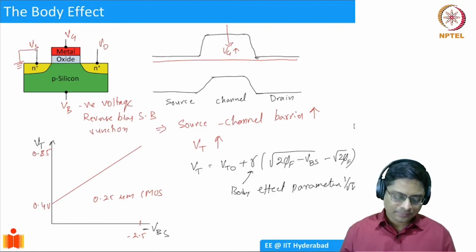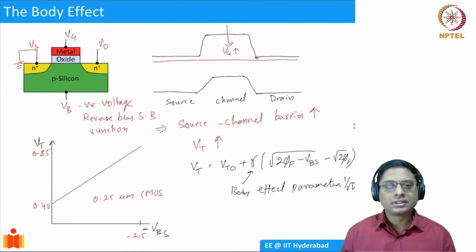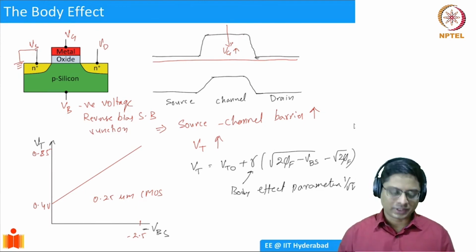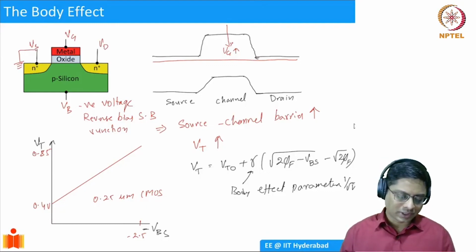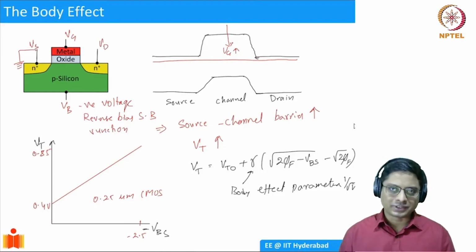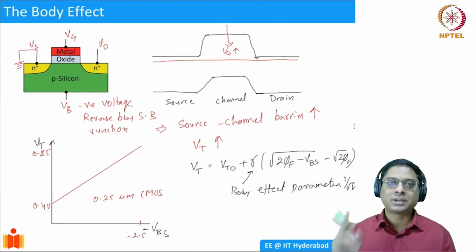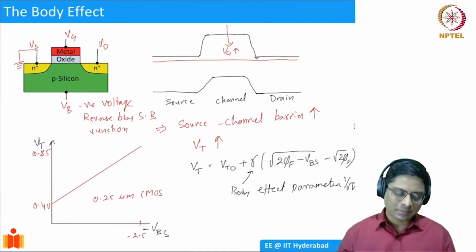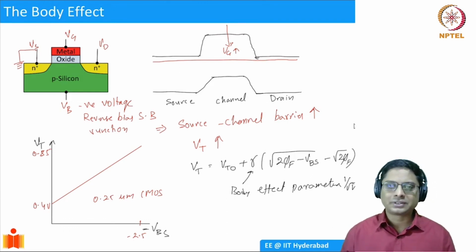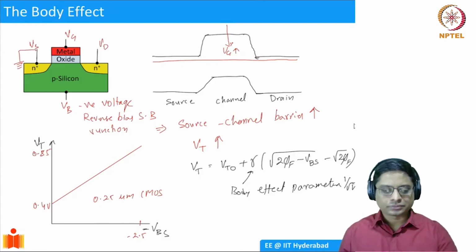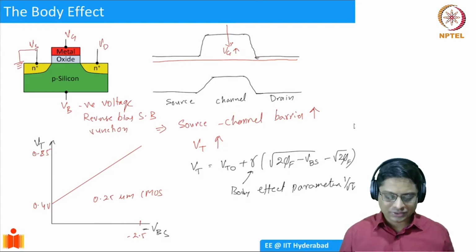So that's why typically in MOSFETs, we ground the bulk for an NMOS device, so that if I apply whatever positive voltage, I'm going to reverse bias it. It will never go into the forward bias. Similarly, for a PMOS device, I'll tie it up to the supply voltage, so that if I apply any other voltage, it will not go into the forward bias. It will always remain in reverse bias. Okay. So this is how the transistor currents can be changed.